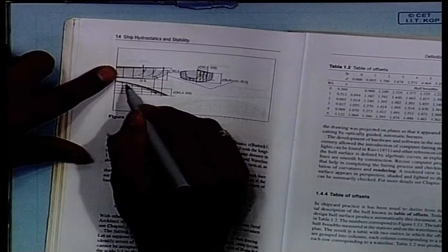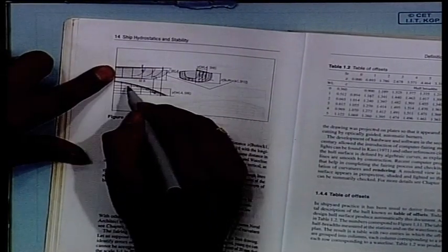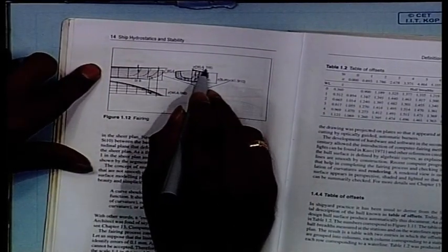It should be in that straight line for one thing, and it should hit that waterline 4, because here you are drawing the waterlines. So, that intersection of waterline 4 and station 8 in this drawing also should match with that. Of course, it is the basic engineering drawing principle, but I am just repeating it. So, this kind of matching should always be perfect. Similarly, in this drawing also you will have this waterline 4 and station 8.